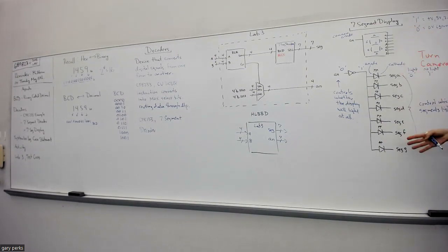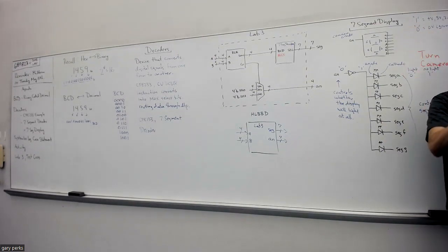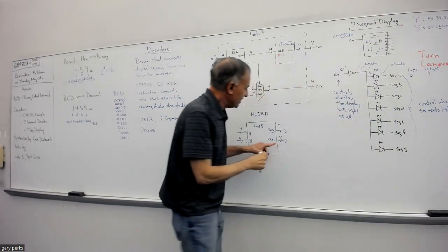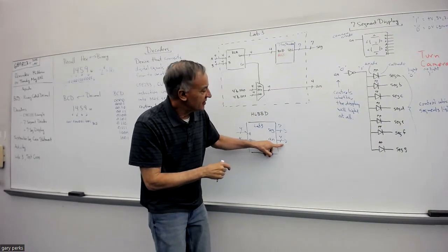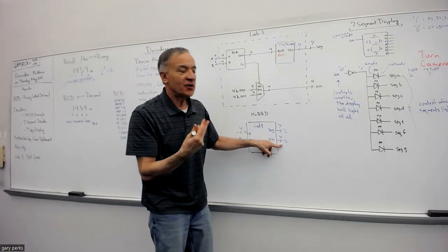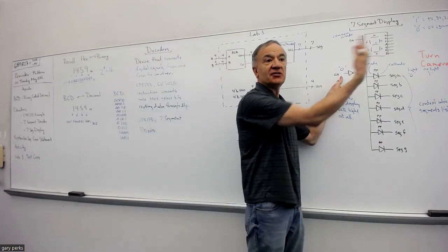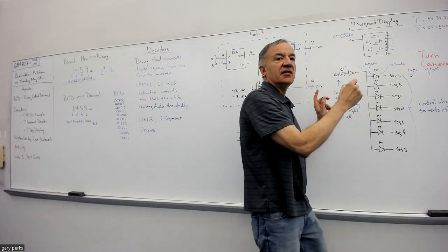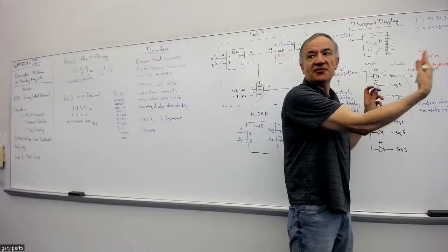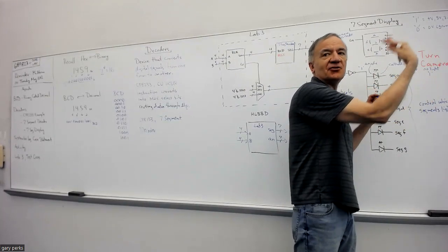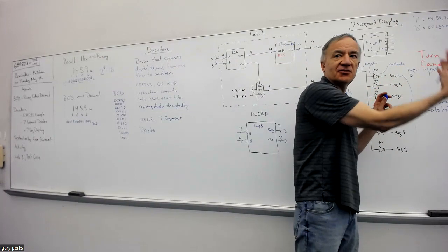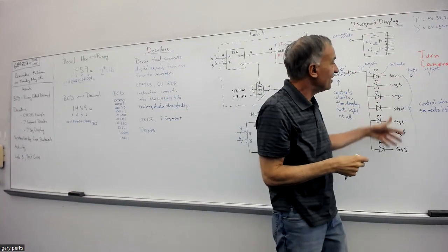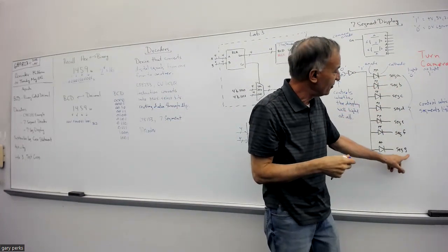And like I said, on the Basys board, you have 4 7-segment displays. They're all the same. So that's why, see this AN output? See how it has 4 bits? The reason why it has 4 bits is because 1 bit is going to display 0. So that would be AN0. AN1's going to another display that we call display 1. AN2 is going to display 2. AN3 is going to display 3, because there's 4 7-segment displays. And they all have 7 segments, so each one has an A, B, C, all the way through G segment.